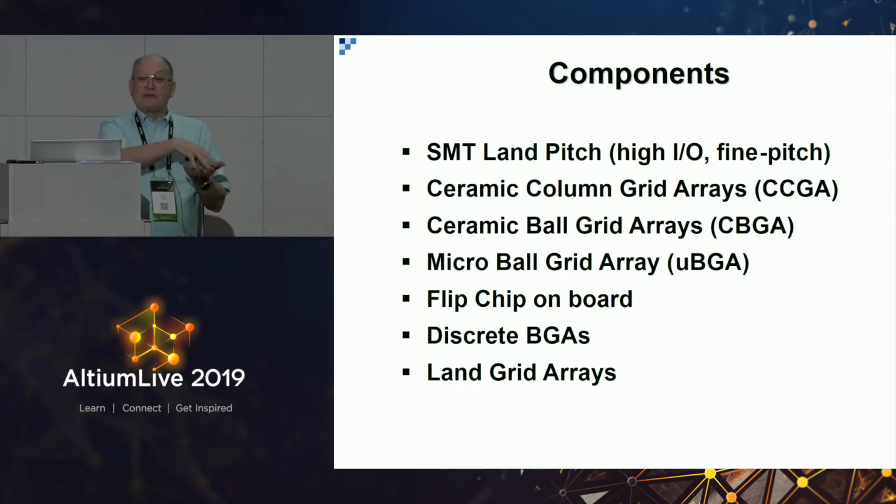Instead of putting the flip chip on a substrate, they put the flip chip directly on the PC board and save that whole layer, and they underfill it. Consequently, you're connecting directly into the silicon, which is why it's 0.08 millimeter pitch, because normally the package will fan that out to a 1 millimeter or 0.8 millimeter or 0.65 or 0.5. But you have to pay for that.